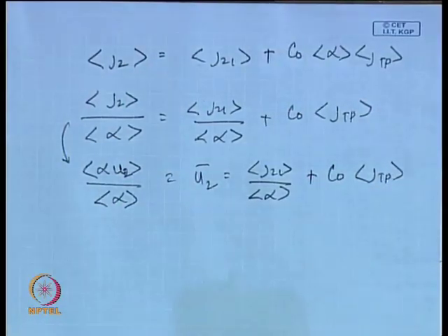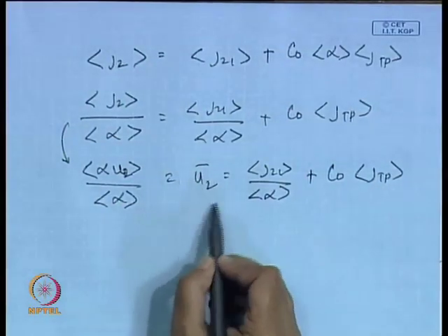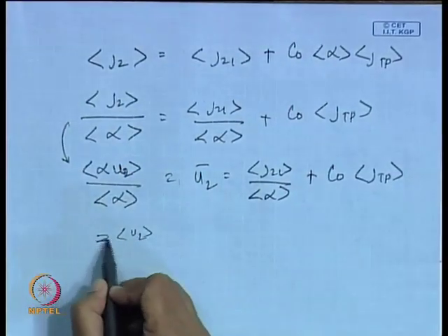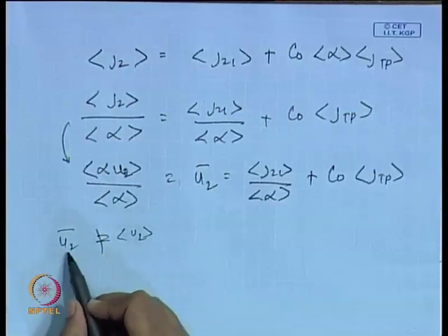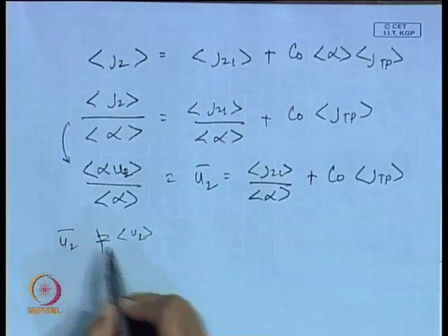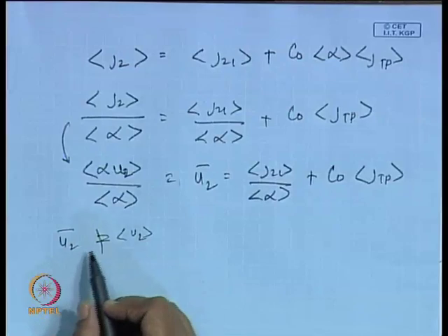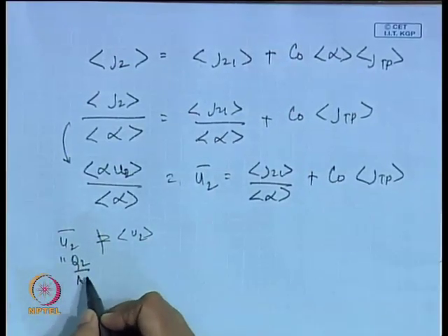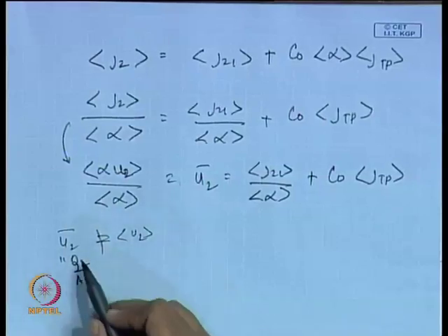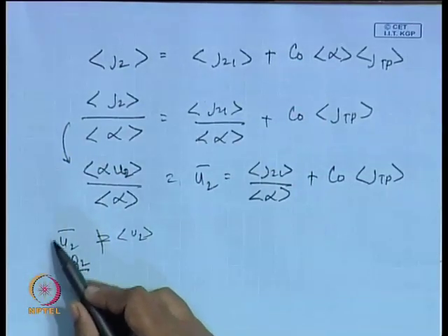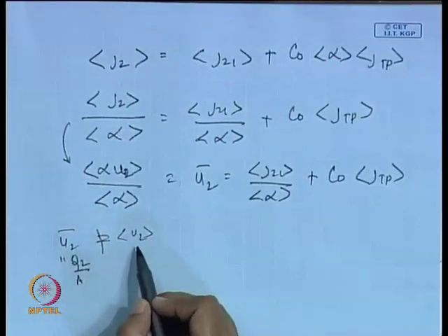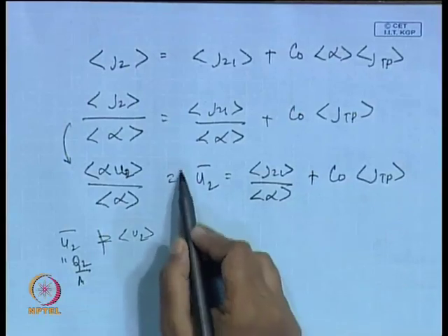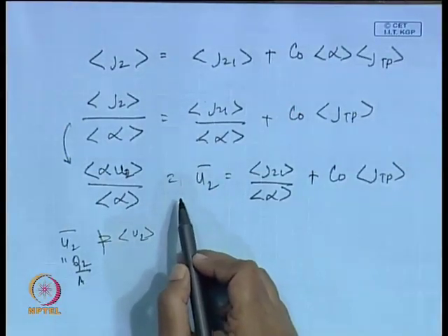So, this can be defined, and we know that this is a much more convenient term as compared to u2 bar, because this can directly be related to input parameters like the overall volumetric flow rate and the mean volumetric concentration. So, it is a much more input parameter as compared to this, and therefore we define this particular equation by considering the weighted mean average velocity.